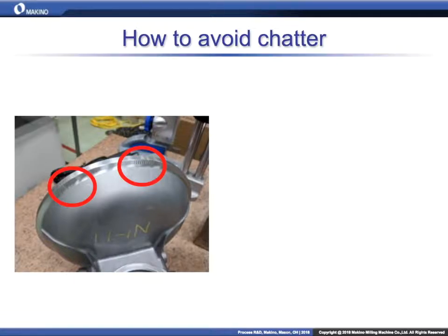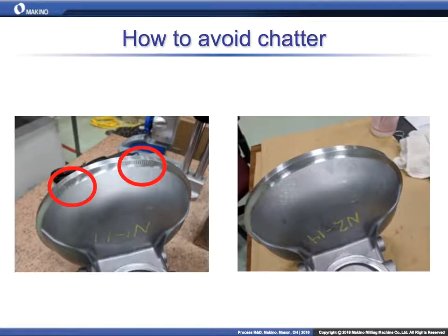So the next picture that we have shows the result with just a change of spindle speed. By properly selecting a spindle speed, you can increase productivity and, let's say, eliminate chatter or find a stable, acceptable finish. Yes. So this was one of those great situations where, because it was aluminum, you're able to go faster. And it was stable. And that's one of those things where it would have been very difficult because you did change the chip thickness a little bit, and it would have been difficult to guess your way to that final solution.